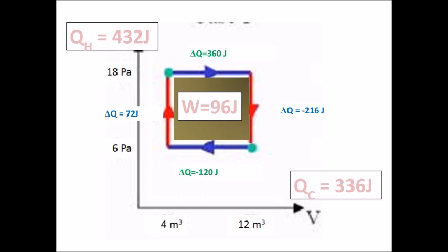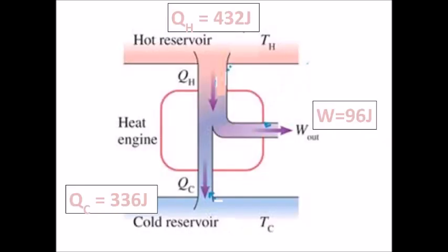The area of that rectangle there, what's our total? We've got 12 on the vertical side, and then we've got 8. 12 times 8, 12 pascals times 8 meters cubed is 96 joules, isn't it? Units check out, yeah? All right, we're good, and we can tell you something more. We can tell you that this machine is 22% efficient. This engine, 22% efficient. Efficiency, what you get out, 96, divided by what you put in, the 432 joules. And that's your efficiency, and that's the last thing I wanted to say about engines.